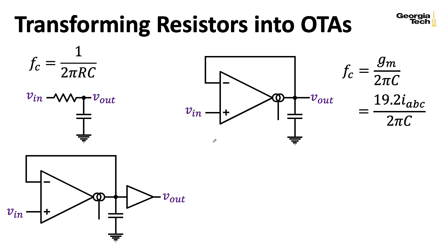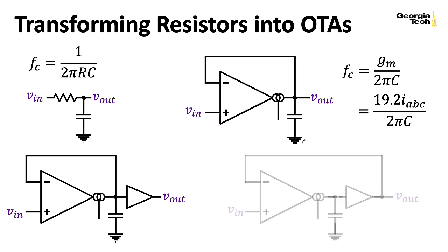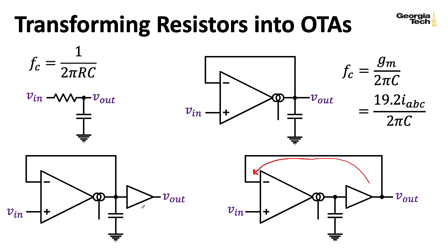Now, when OTAs are used as part of an integrated circuit design, I see things like this quite often. But every time I've seen people build filters on a PCB where the most integrated element is an OTA chip like a CA3080 or an LM13700, I always see them take the feedback voltage from after this buffer. One thing that I have thought of is that something like the LM13700 doesn't have infinite input impedances. There is a bit of current flowing through here, so maybe taking the output from the buffer here is a good idea, so you don't wind up stealing current that should be going through the cap that winds up flowing into the negative terminal when we don't want it to.